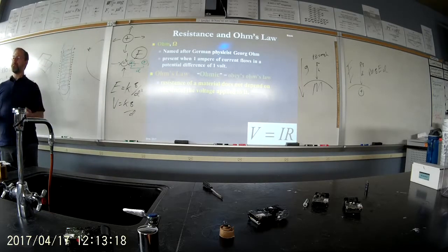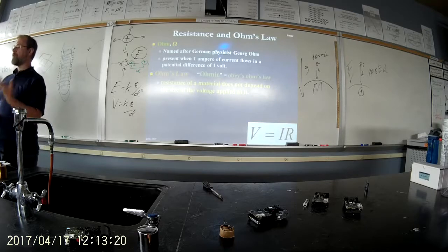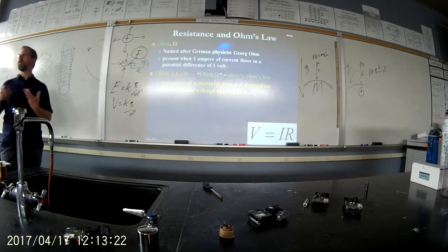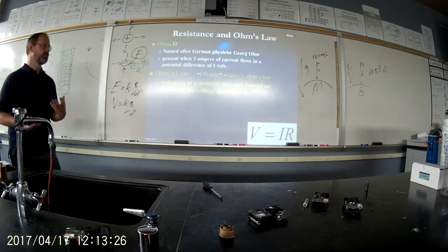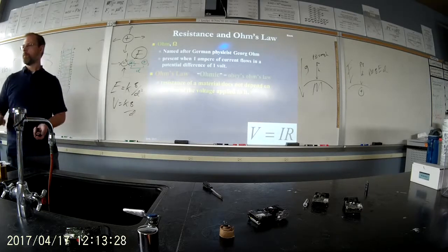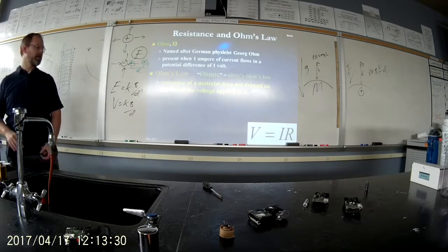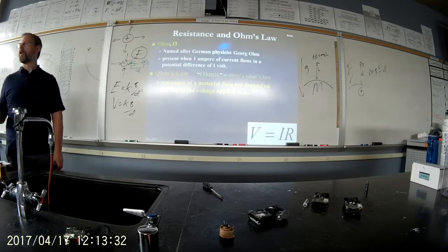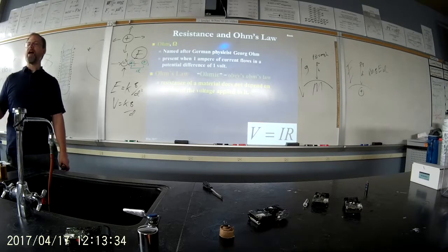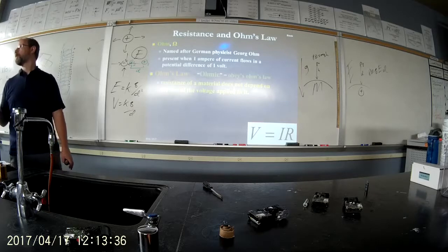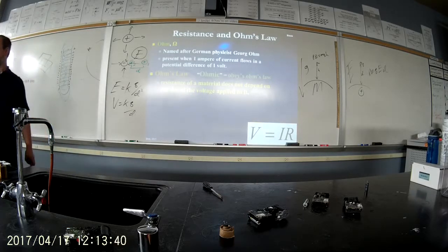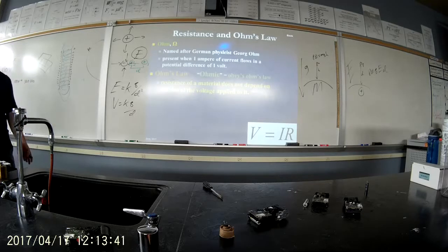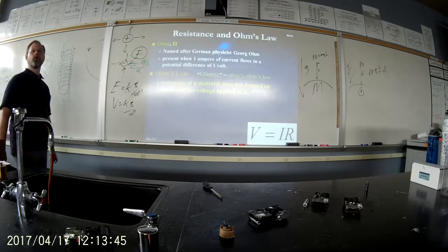It has the same material constants, the same resistance, the same conductivity if you apply 1 volt to it as if you apply 100 volts to it. So again, we tend to say V equals IR is Ohm's law, and that is a critically important formula. But what Ohm's law really says is that something that obeys Ohm's law doesn't change its resistance depending upon what voltage you apply to it.